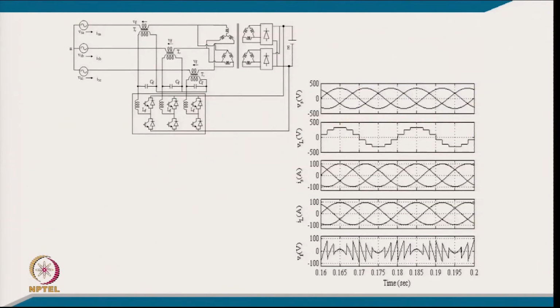So, this is the typical circuit here. The battery is not only connected across the load, but it is also connected in series with the series active filter on the DC link, and the DC link is common. With the help of the series active filter, we inject a voltage in such a manner that the currents become sinusoidal, balanced, and in phase with the voltage. So, perfect unity power factor is achieved and harmonics are also reduced. Virtually, the series active filter is working to eliminate the current harmonics.